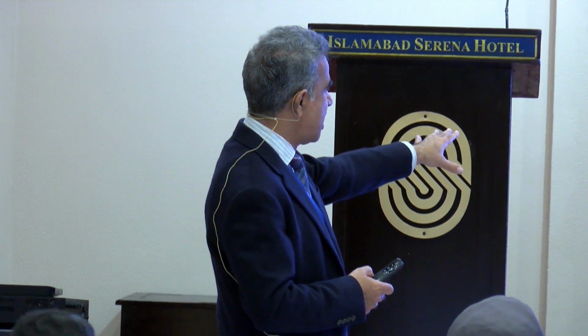So the tool body has centralizers, and then a receiver array and a transmitter array. Transmitter arrays are monopole and dipole. Monopole must be used for compressional. Dipole is additionally used for slow formation shear, and otherwise shear will only come from monopole.